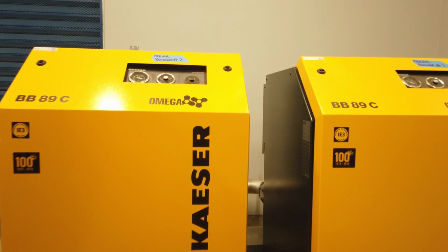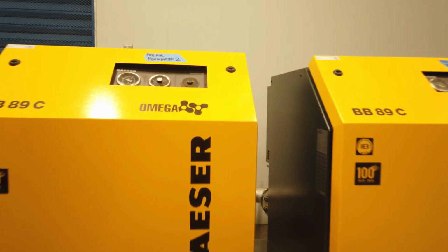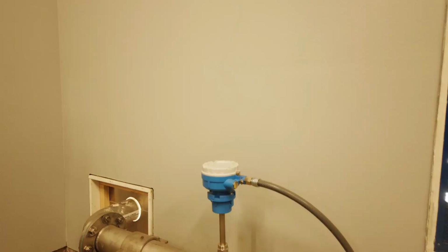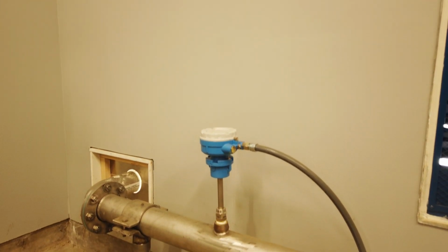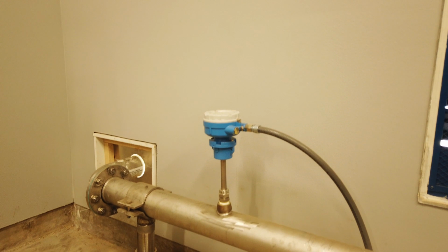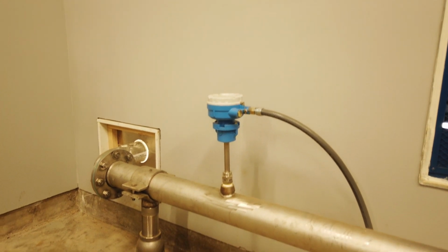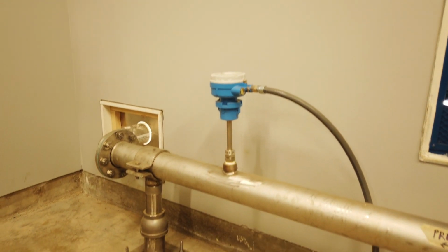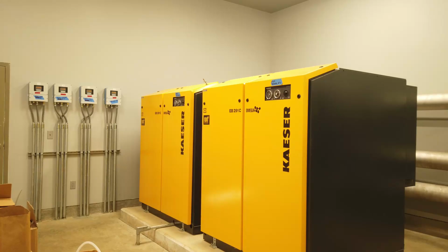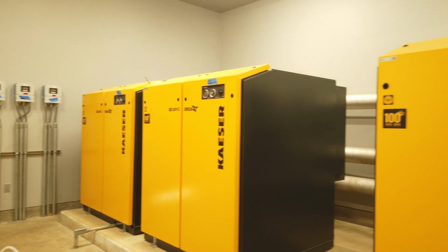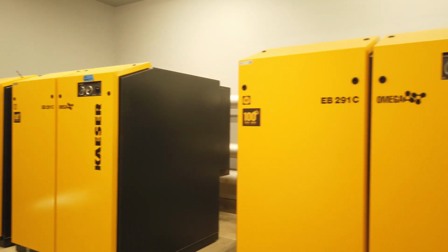They manage the dissolved oxygen in the PreAeration tank to accomplish the 2 milligram per liter set point. The air is adjusted based upon the airflow sensor, a thermal mass airflow sensor, installed on the discharge line of the PreAeration blowers. The MBR air scour blowers are much larger, at 50 horsepower each.